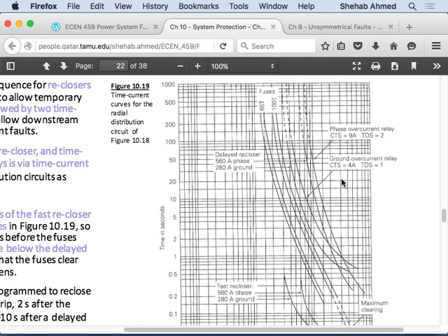If there's no zero sequence current, that means the fault is a three-phase fault, or a line-to-line fault. You want to detect that using the phase measurement, so you put a phase overcurrent relay. So I had to put a current sensor on the neutral. I had to put current sensors on the phases. How many do I have to put on the phases? All three or two, right?